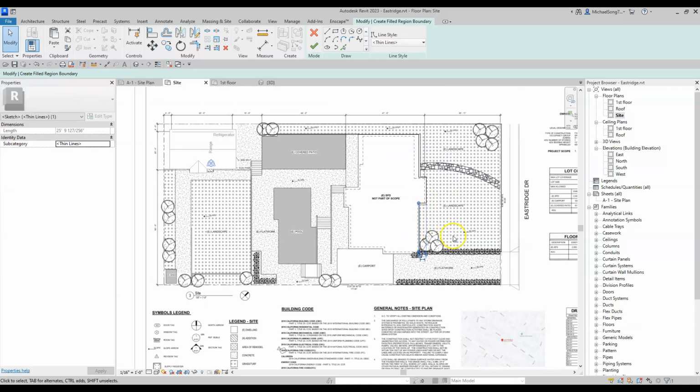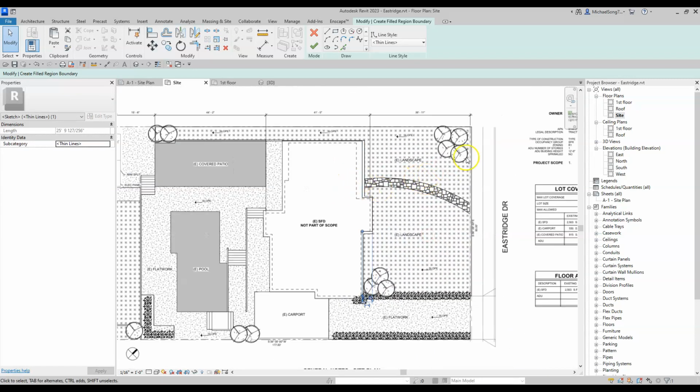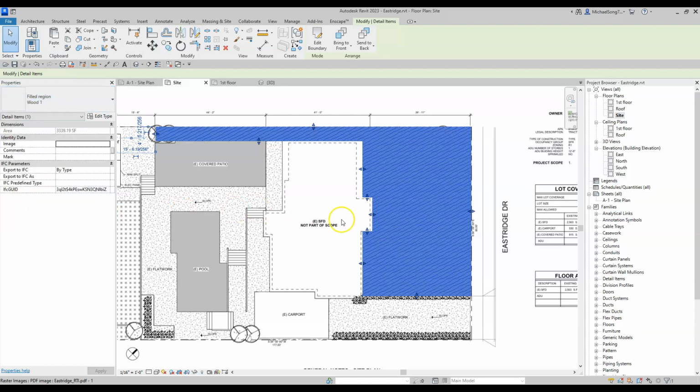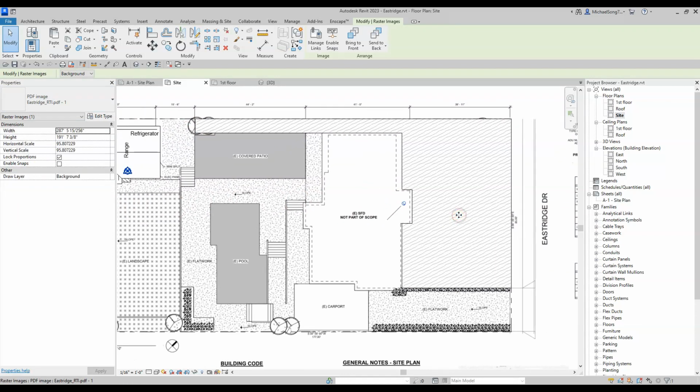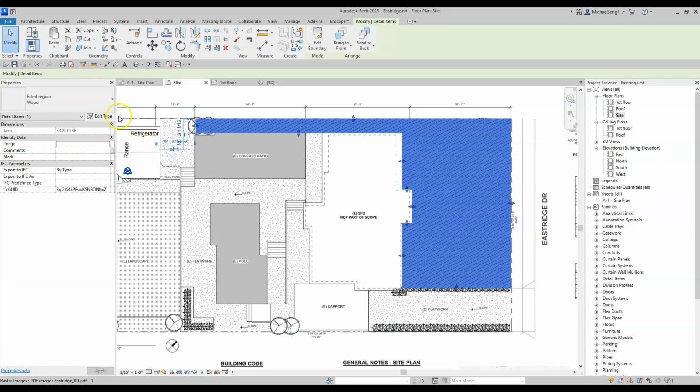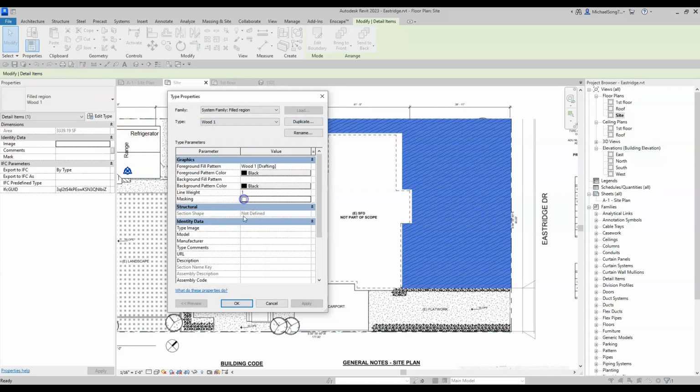All right, so of course, please be more accurate than I will. I went right, instead of cutting this piece of pie and then doing another piece of pie, because I'm going to draw right over that, I just created one large hatch. I don't have the grassy pattern here, so you guys are going to import from the pattern files that I provided for you to make that a grassy patch. I won't do it for this demo because you should know how to do that by now. But what I will do is make this not masking so you can see through it.